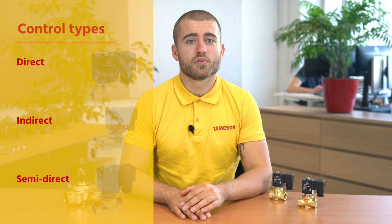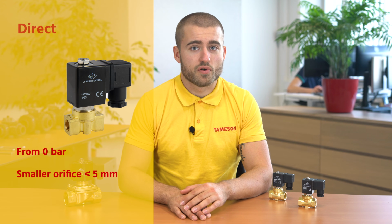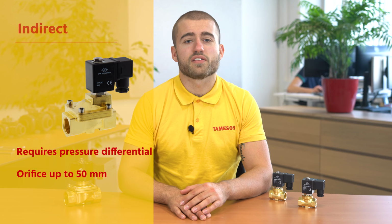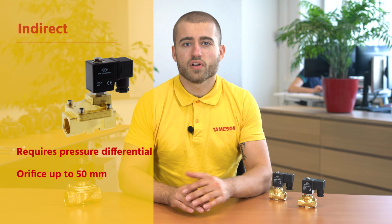First of all, the different control principles. There are three different solenoid valve control types: direct, indirect, and semi-direct. A direct acting solenoid valve works from 0 bar, is generally for smaller flow rates, and doesn't require a pressure differential for operation. An indirect acting solenoid valve requires a pressure differential of half a bar and has a small solenoid for a comparatively large flow rate.